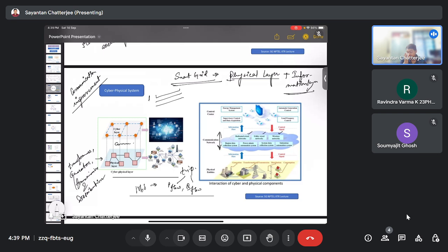These are not 3 phase lines, I'm just saying line 1. All these lines are operating in parallel, carrying a load over an area, from the generating plants to the load center. So if line 1 gets tripped, that would result in overloading in the other 2 lines, and in this way we would be following up into a cascading failure.